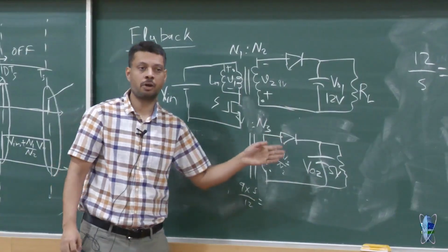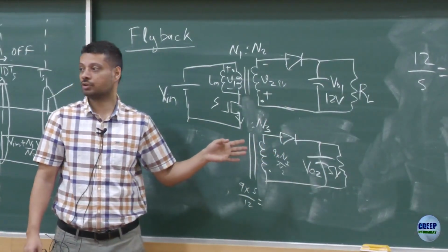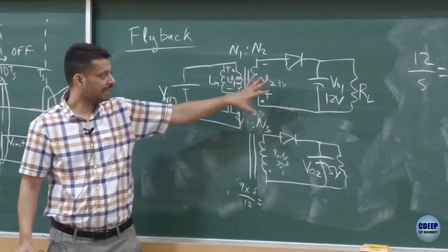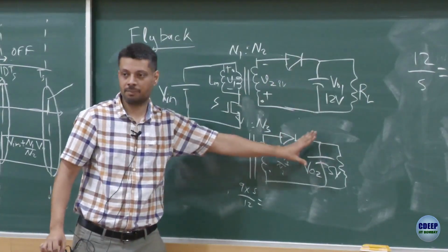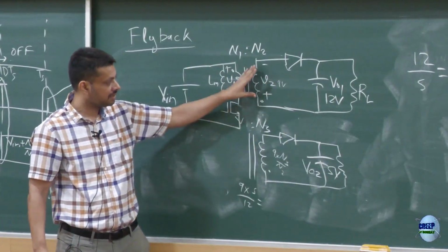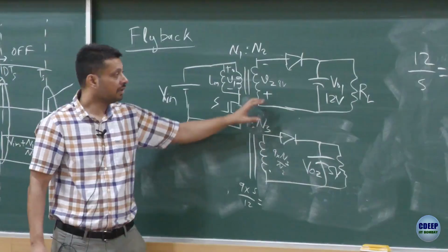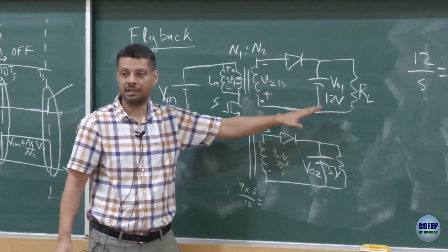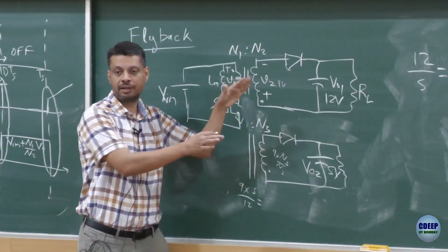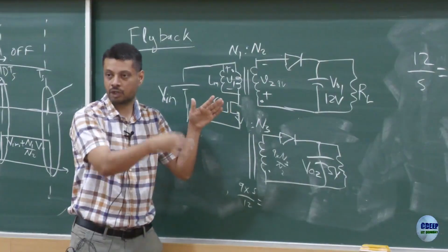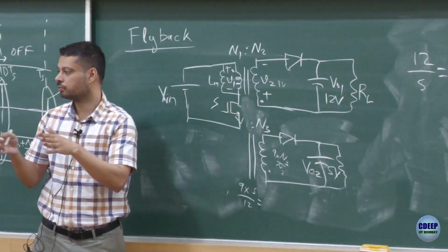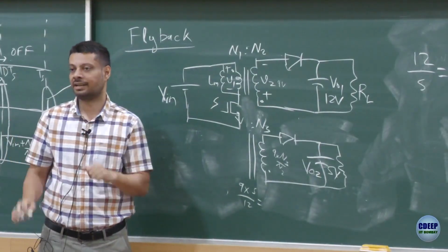This is very similar to the common cathode configuration, but it's a little bit different picture, but it's the same principle. Basically, there are two diodes. On the output side you have some voltages; on the input side, in this case they don't have common voltages, but there is a turns ratio, so common cathode configuration. So whichever output is less than the desired value, that diode will conduct, shoot it up, bring it to 12 volt. Once it is 12 volt, then both diodes may conduct simultaneously. If one of the voltages drops suddenly, 5 volt goes to 3 volt, then again the majority of the current will start flowing into that output, it will bring it up, and then it will try to maintain both of them.